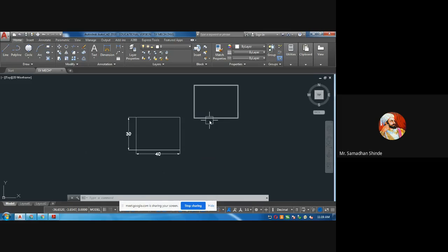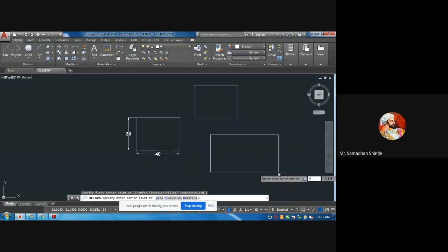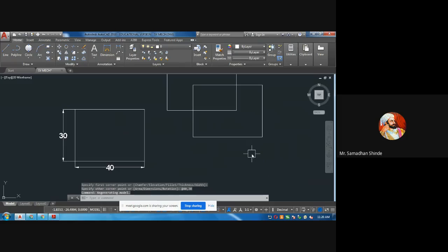Another thing is, if I click on this, it is unique, it is totally getting selected. But here, the total is not getting selected. That is the difference between the simple command and this command. Okay, understood what this rectangle command is? With rectangle, only 2 times I have to give a dimension. I click the rectangle command, click only once, horizontal dimension 40, tab button 30, tab, like this.